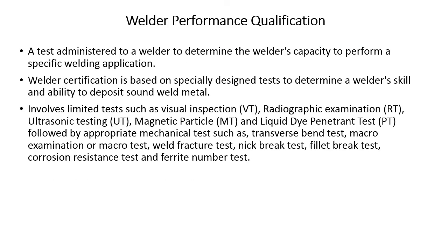Welder performance qualification. A test administered to a welder to determine the welder's capacity to perform a specific welding application. Welder certification is based on specially designed tests to determine a welder's skill and ability to deposit sound weld metal. It involves limited tests such as visual inspection, radiographic, ultrasonic, mag particle, dye penetrant testing, followed by appropriate mechanical tests such as transverse bend test, macro examination, macro test, weld fracture test, nick break test, fillet break test, corrosion resistant test, and ferrite number test.